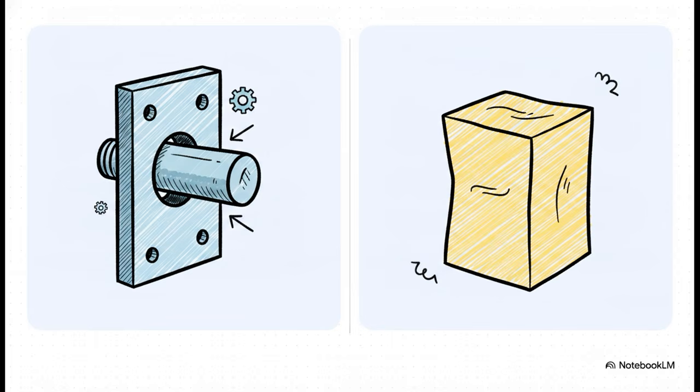They guarantee that a bolt will actually slide through a clearance hole, or that a bracket will sit totally flush against its meeting assembly. On the flip side, you have cosmetic or independent form controls. Think of a loose flatness or straightness callout that doesn't even reference a datum. Distinguishing between these 2 is absolutely crucial. Why? Because it dictates your manufacturing and inspection priorities.